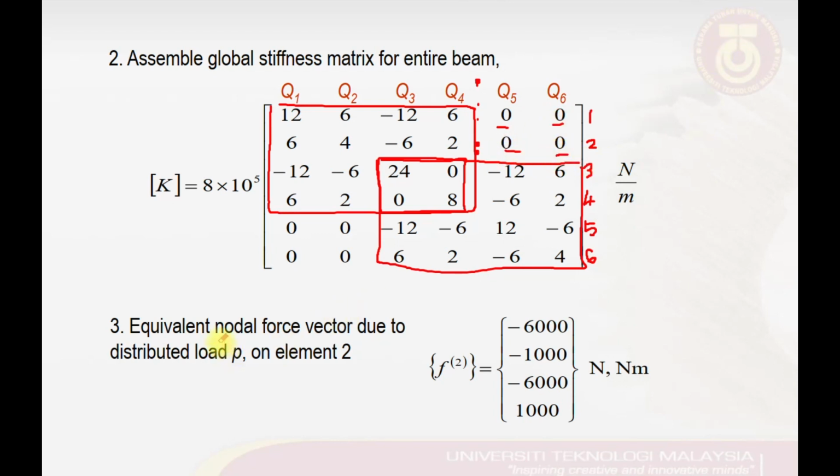So the equivalent nodal forces and moments will carry the same value as calculated before in the previous slide, but will carry the negative sign here, which is to match with the positive sign conventions as we agreed before.